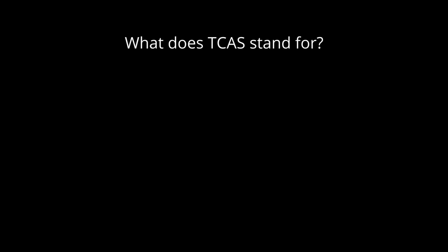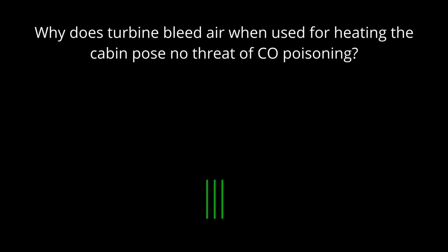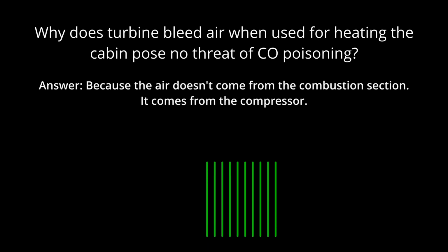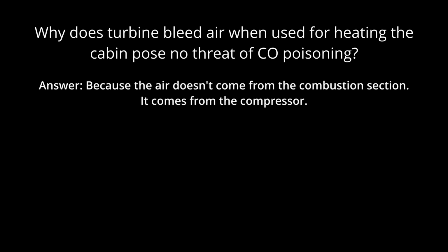Y'all know what the acronym TCAS stands for? Traffic collision avoidance system. Why does turbine bleed air when used for heating the cabin pose no threat of carbon monoxide poisoning? It doesn't come from the combustion section. Okay, it comes from the compressor. The compressor, okay, that's right.